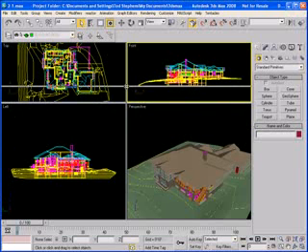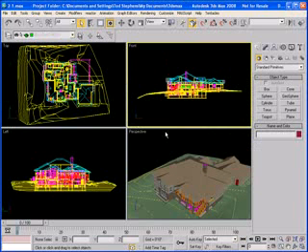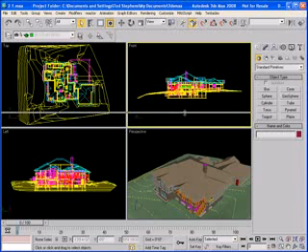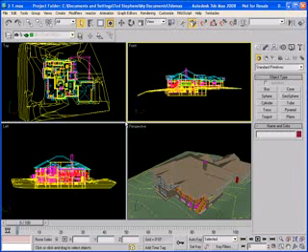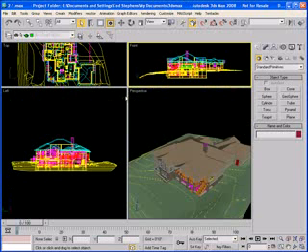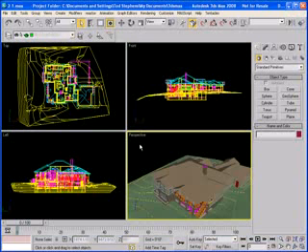Now also notice in your viewports, I can hover my mouse kind of in the center of the viewports. The icon changes there to a series of arrows, and I can move these around. So if you wanted to resize your different viewports, you could just click on them there and move them around. If I right click after selecting that and reset the layout, it just goes back to where it's symmetrical. Every viewport is the same size. I just right clicked in my perspective view to make it the current view.